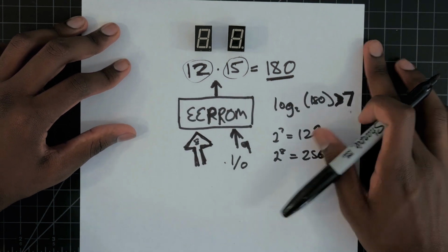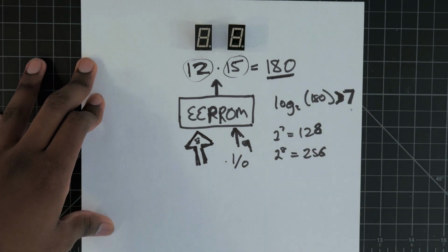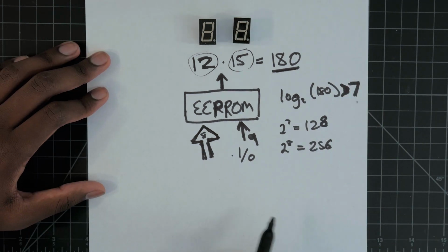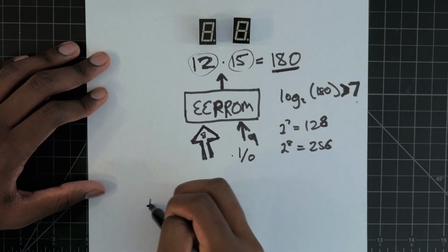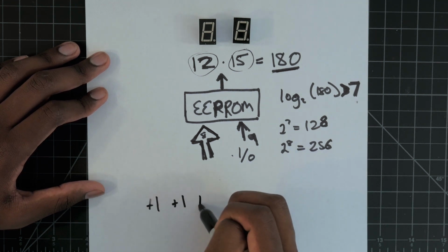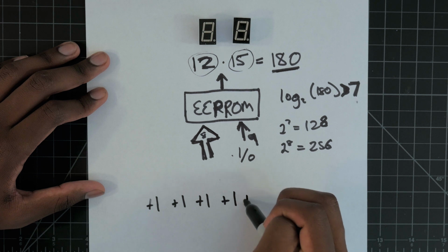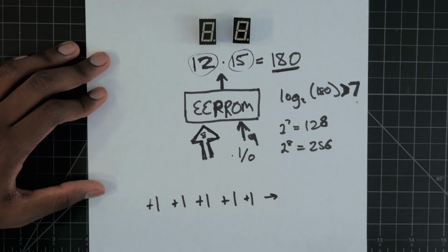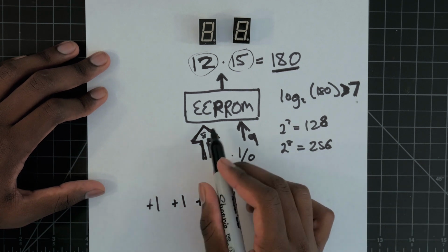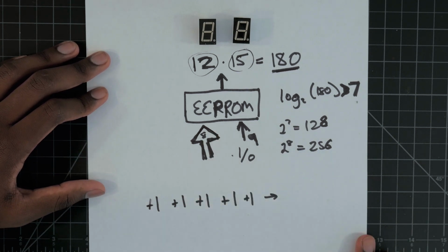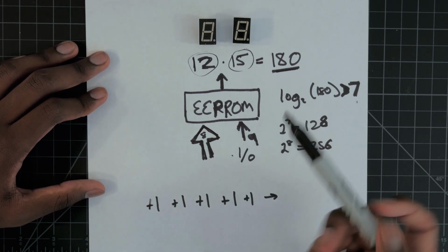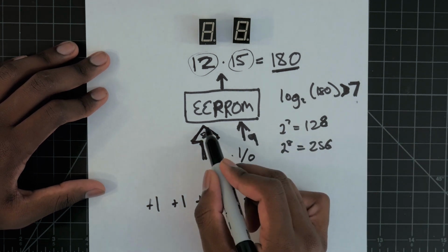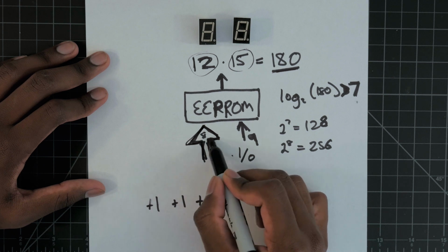So the next question is, where do these 8 bits come from? Now it's time, so as each minute passes, we're just going to be adding 1 minute plus 1 minute plus 1 minute plus 1 minute, and if we total these up, we'll get whatever time we're at in minutes. Something that just keeps adding on a uniform clock is just a counter. And because we're talking about binary, we're going to use a binary counter.